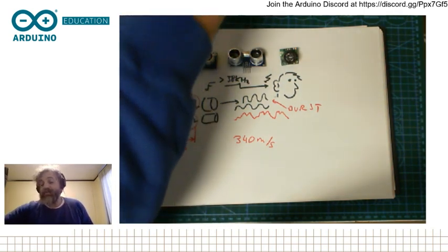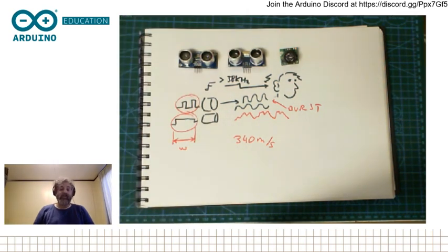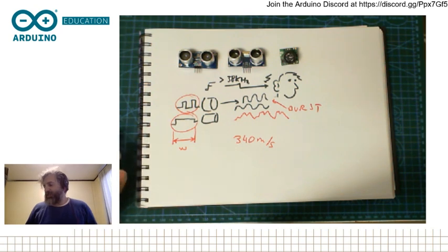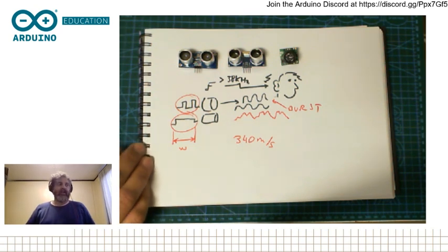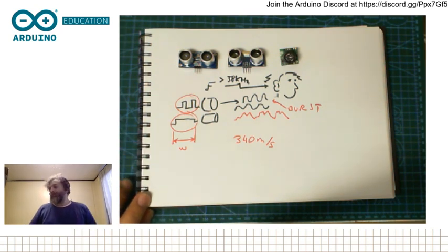Then ultrasound is extremely sensitive to different conditions. Ultrasound is very sensitive to, for example, humidity. So right now our shed is pretty humid and it's raining outside. So probably the quality of the measuring should be handled with a different kind of formula than the one that comes by default. But this is not a scientific measurement, it's just for checking the distance to objects, so we will live with that. Okay, but you should keep this in mind.